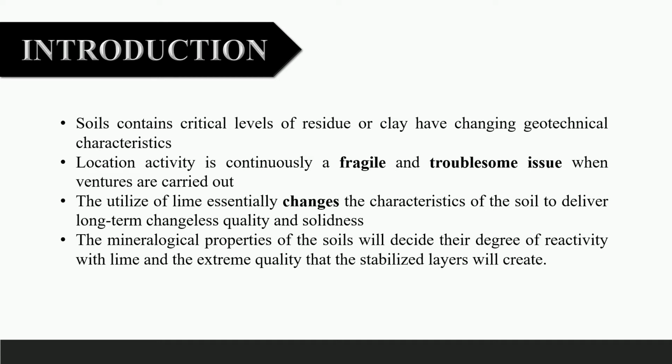The use of lime essentially changes the characteristics of the soil to deliver long-term permanent strength and stability, especially with regard to the action of water and soil. The mineralogical properties of the soil will determine their degree of reactivity with lime and the ultimate strength that the stabilized layer will develop. In general, fine-grained clay soil is considered to be a good candidate for stabilization.